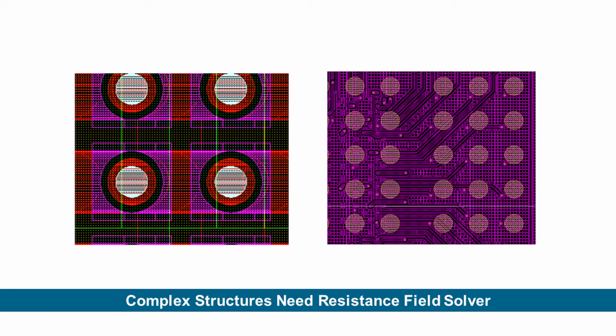For a 2.5D mesh, a single plane of resistive elements is created in the XY direction for each metal layer. Contacts in the Z direction are then made to the mesh with additional resistors in the Z direction only for vias. 2.5D simulation runs much faster than full 3D since the number of nodes is much smaller. Users can choose specific nets and/or layers for RFS to extract.